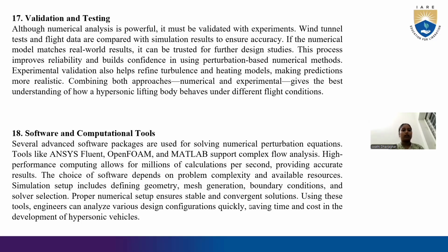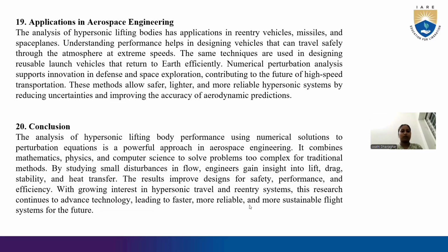Validation and testing. Although numerical analysis is powerful, it must be validated. Wind tunnel test and flight data are compared with simulation results to ensure accuracy. If the numerical model matches real-world results, it can be trusted for design studies. This process improves reliability and builds confidence in using numerical methods. Experimental validation also helps refine turbulence and heating models, making predictions more realistic by combining both approaches, numerical and experimental.